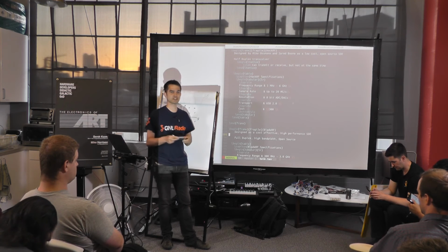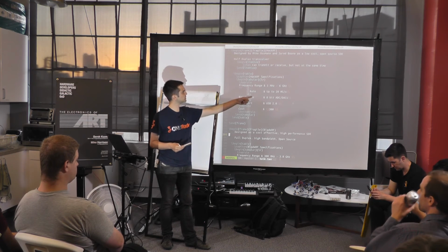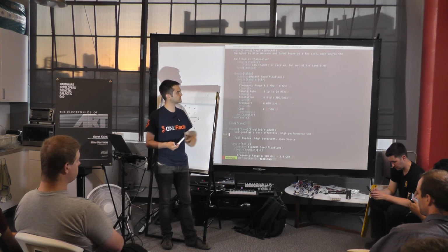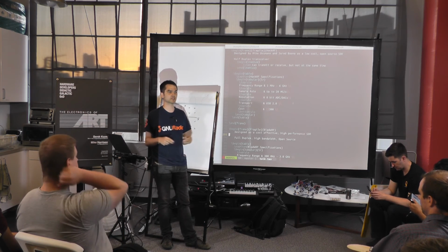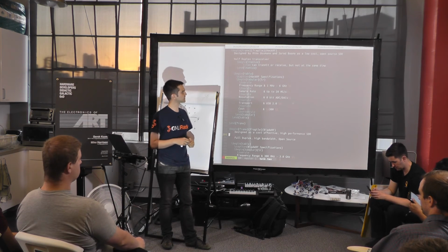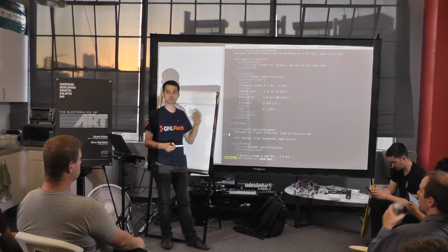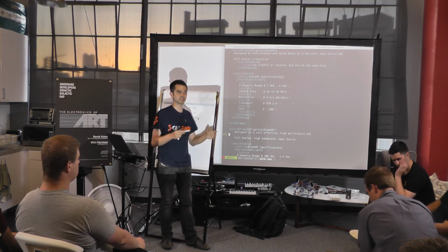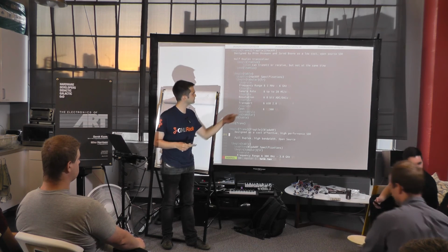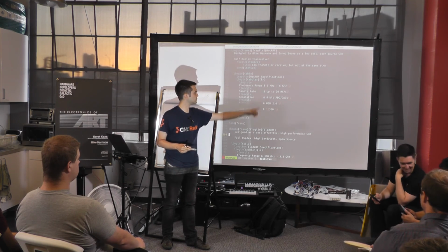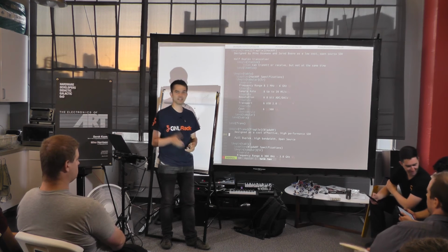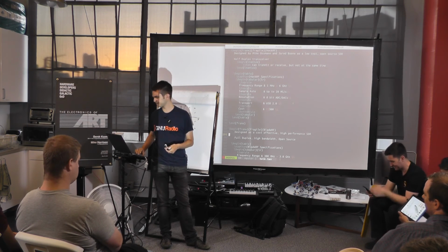Transmit or receive one at a time from 1 megahertz to 6 gigahertz up to 20 megasamples per second, so you can view 20 megahertz of the spectrum, which is just barely enough to see a full Wi-Fi signal. And GNU Radio actually has blocks for demodulating the Wi-Fi, so you can actually see some of the channel information in the data. Still over USB 2, still with 8-bit ADCs, and that's $300 right now.